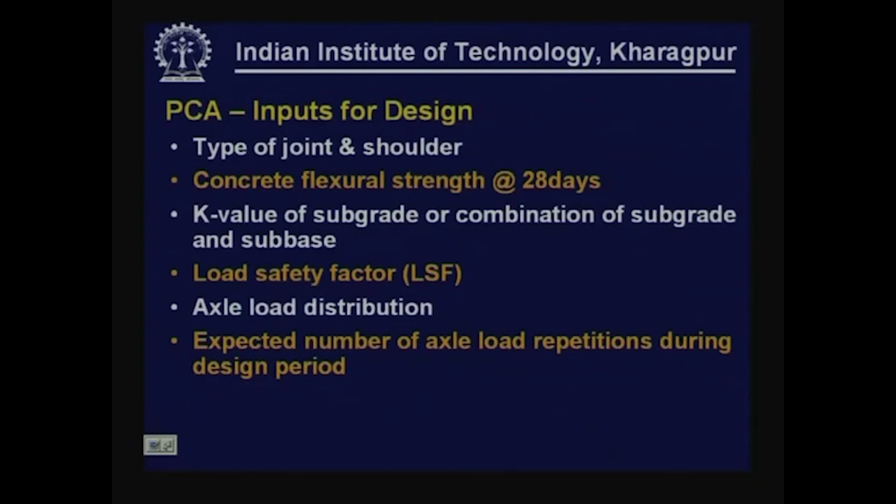We have to select a load safety factor depending on the type of facility. We have to have information on the axle load distribution. We also have to have projection about the expected number of repetitions of different axle load groups during the design period.